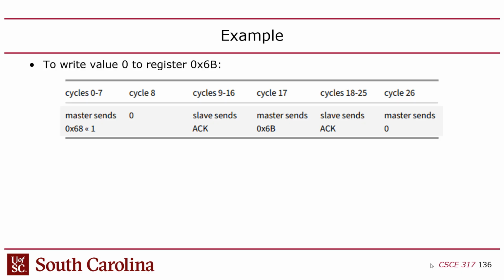So then I'm going to send 6B in the value I write. Make sense? Right? So basically, I've used the address byte to send the device address. The second byte, which is the data that I write, I use that to send 6B. What's 6B? That's the register I'm targeting on the device, right? Okay, then in the third byte, I send a 0. Right? So it's 3 bytes. It's one transaction, 3 bytes.